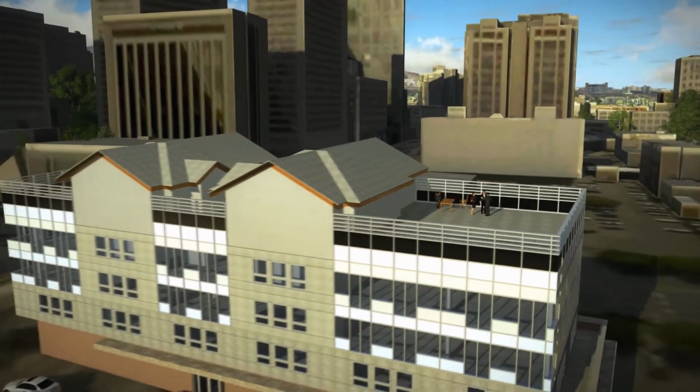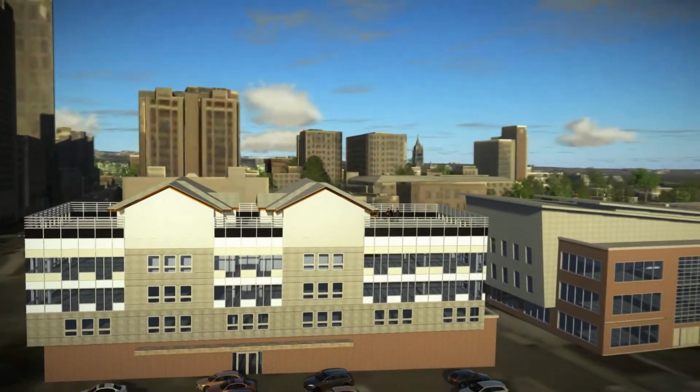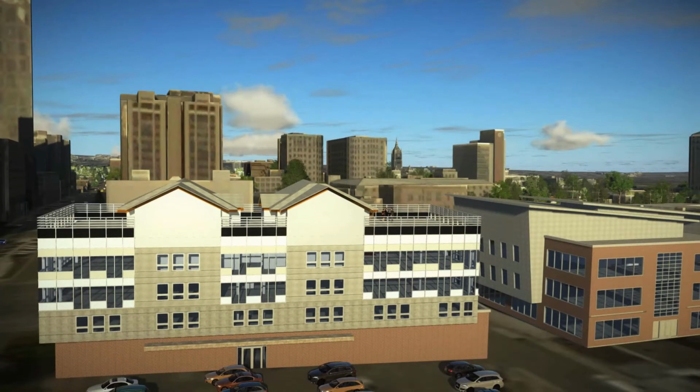used ContextCapture, which is another solution for reality modeling at Bentley Systems. And what we do there is we take pictures with a digital camera and we create a 3D mesh out of these pictures. So in this case, you can take a drone or whatever, you fly over your area or something like that, and then we create the 3D mesh, and everything can be merged together. So this having said is you can have your AECOsim Building Designer project in a real life environment.